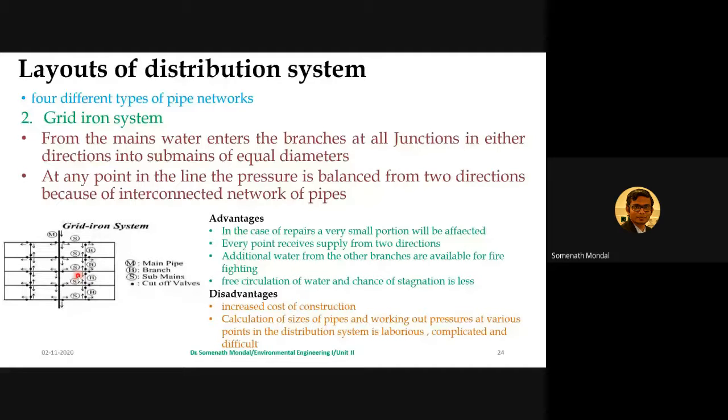Fine. Next, the design is difficult and costlier. The calculation for determining accurately the size of the pipes and the pressure at the various key points is really a tedious job and may require the services of design experts and even computers, since each point is connected from two different directions. So there comes the complicacy, and that is the reason it is not that easy. So we need sophisticated software, or professional designers to help in this aspect to finally calculate. So the overall design is a little bit tedious and complicated compared to the previous one.